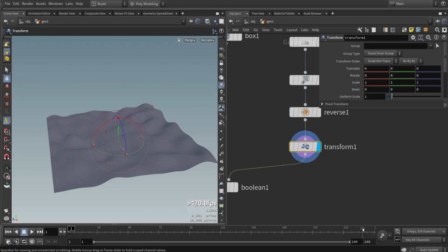Which also comes to the next point, which is the number of frames that we're going to use. So we will bake this out to render this out in a spreadsheet, which will basically be a flipbook. So we have a collection of images. To put some thought into our images, we're gonna say let's use a 6 by 6 spreadsheet, which means that we will have 36 frames. So 36 frames in total.